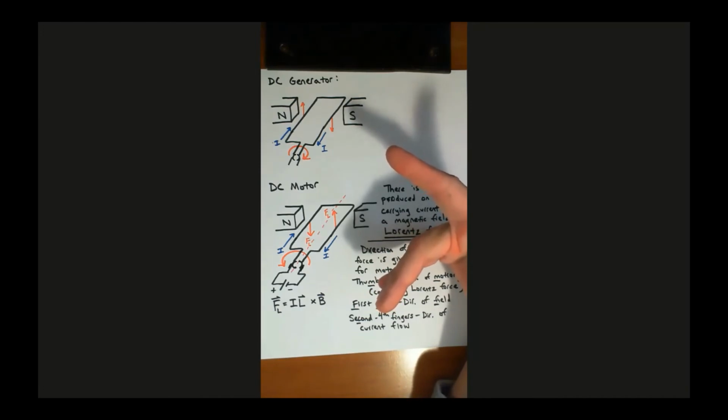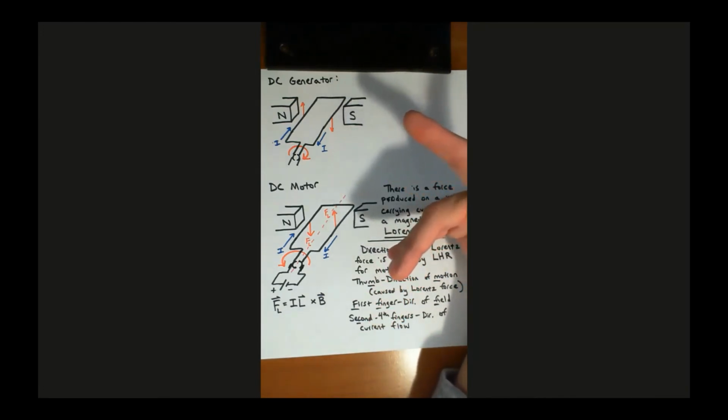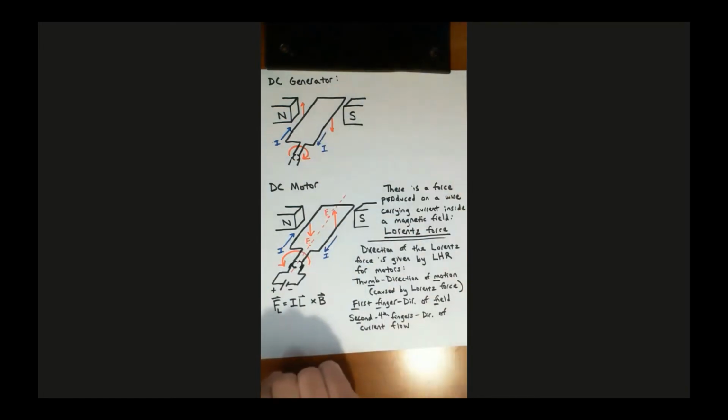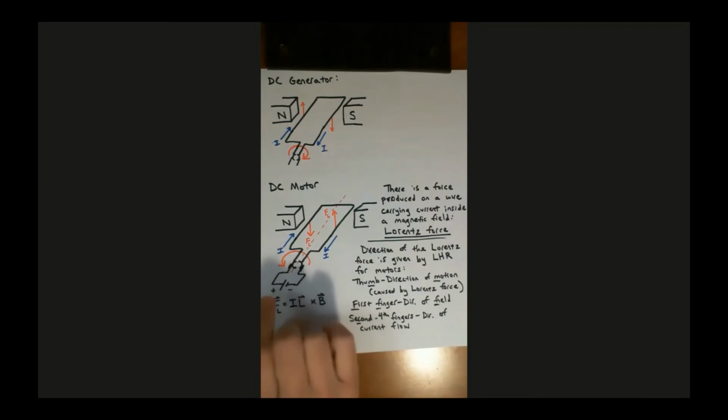Furthermore, let's go ahead and apply the right-hand rule, because I know I have generator action happening inside this motor, and see what the polarity of the induced voltage is as this motor starts spinning faster and faster. I'm going to apply the right-hand rule for generators to this motor as it is spinning. We don't have generator action until this motor starts spinning, and spinning pretty fast.